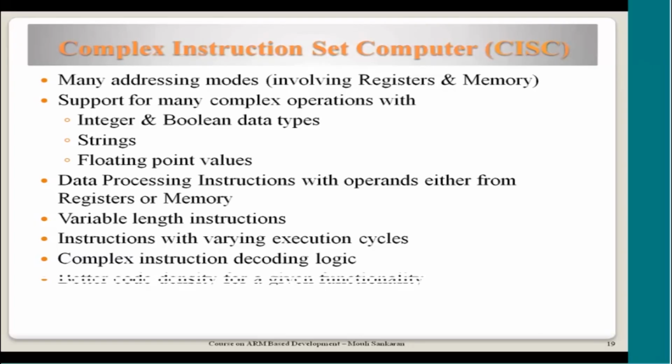built within the chip to understand the instructions coming from the memory. Now, what is the advantage of the CISC operation? There are some advantages because multiple operations are encoded in a single instruction. You get a better code density when you use those instructions in the application. What I mean by code density is the amount of space occupied by the code when you compile your high level language or an assembly instruction. When you assemble it and get a binary image, that will be much smaller because the compiler or assembler would have chosen a correct instruction for performing your job, and effectively we get a better code density because of that.